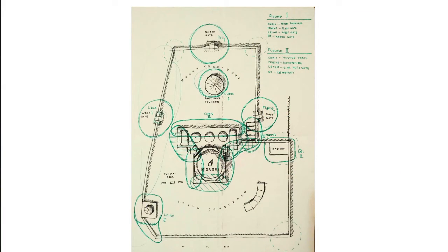Sure. Yeah, so as we got into the photogrammetry process, we broke it down. One of the other goals while we were there was to teach the students a documentation method that they can take with them. So we had to achieve that from start to finish, including an example project within a week. So photogrammetry suited itself pretty well to that, whereas something like laser scanning is a lot more time intensive, both to capture and then process. So photogrammetry lent itself pretty well.